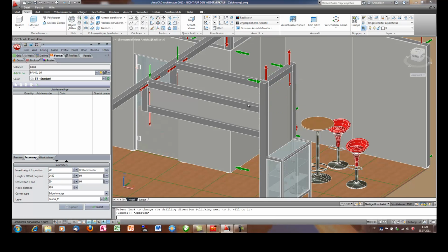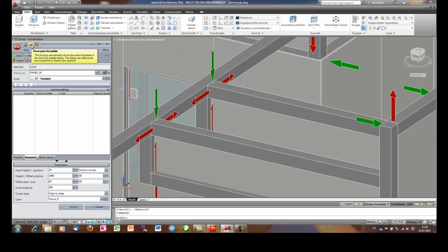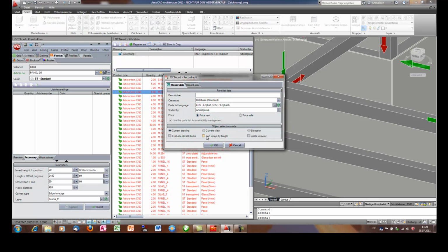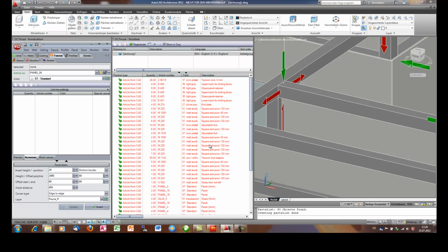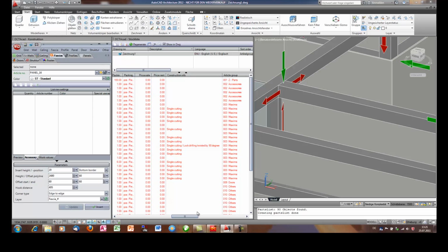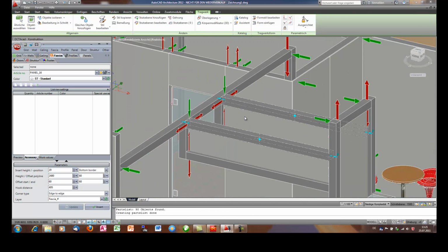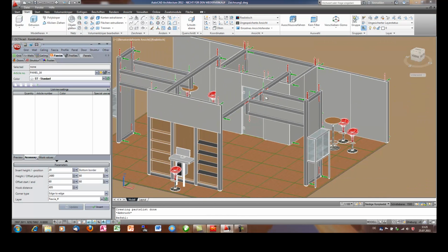And this you can also see in the part list, because if you go to the part list and you regenerate it, full drawing, then you can see at the end of the part list that the tension locks were twisted by 90 degrees. Now let's finish with these two functions, and we erase the arrows now with profile and erase arrows, and we change to another useful function.